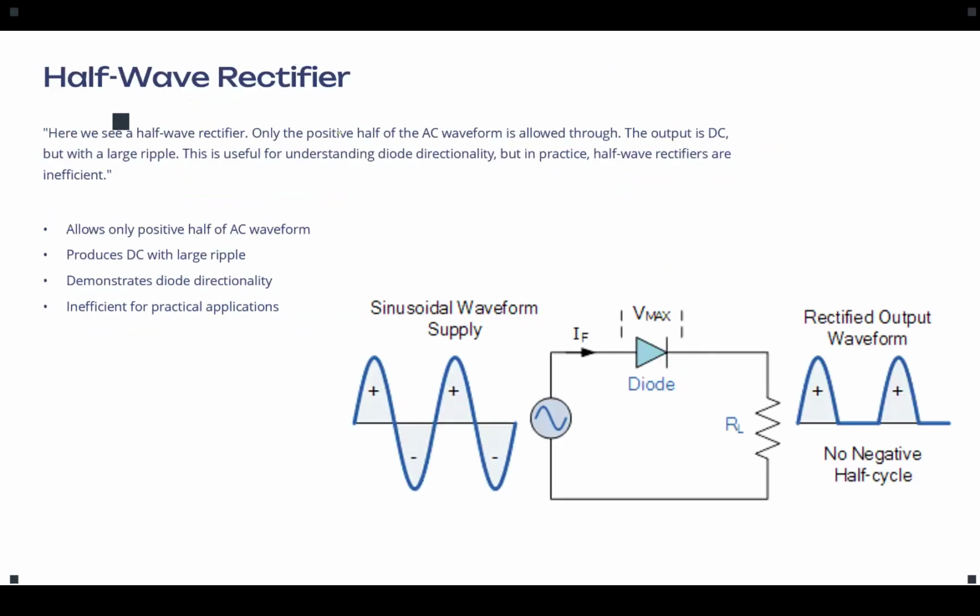Now, let's go deeper on those applications. We said a diode can be used in a rectifier. We have two types of rectifier. One is the half-wave rectifier, which is a simple diode; just one diode does the work. You have an AC signal as an input and a series diode with that source.